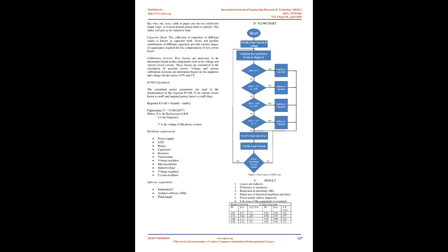Microcontroller, AVR: the ATmega328 is made by Atmel in the Mega AVR family. It is utilized to perform various tasks in independent frameworks. Here, it calculates the phase delay between current and voltage and calibrates it into phase angle and the corresponding power factor. Based on the calibration, the capacitor banks are switched on.